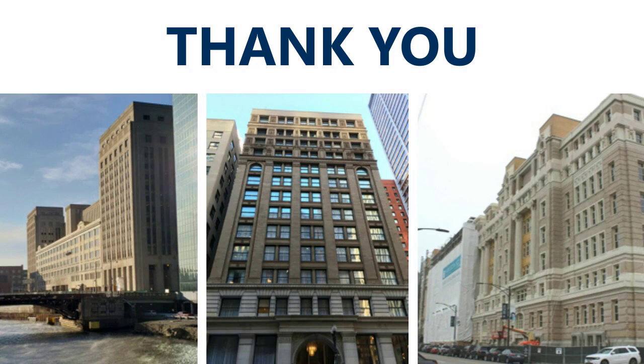We try to salvage as much as possible and reuse for multiple purposes. One, cost usually, but two, if we're dealing with historic, you want to salvage and maintain as much historic fabric as possible. If it's not a historic building, sometimes salvaging and replacing brick, let's say, is cost prohibitive or not worth it, because buying brick that's fairly cheap as far as cost is concerned to replace existing brick might be more economical for a contractor rather than having somebody clean off the mortar. But again, we try to salvage as much as possible, but it's not always possible and it's not always known based upon a visual inspection.